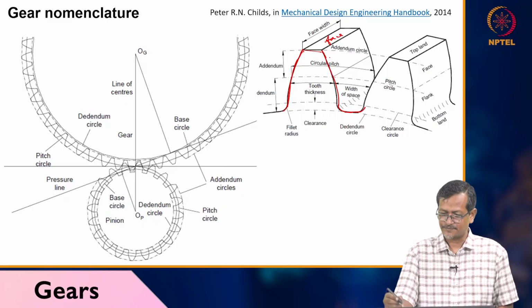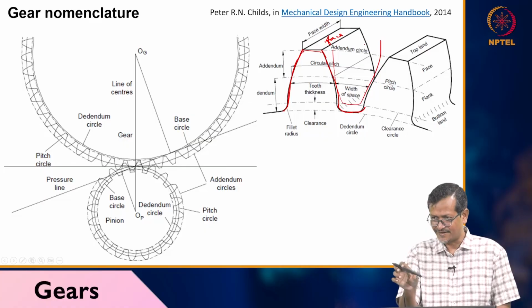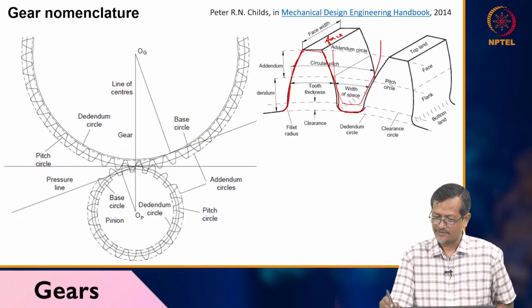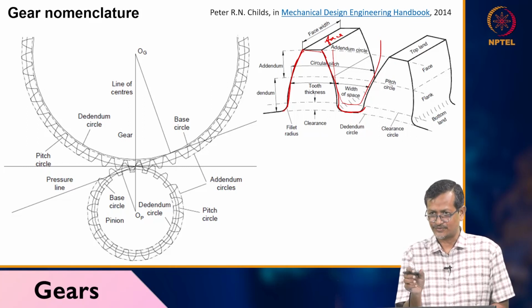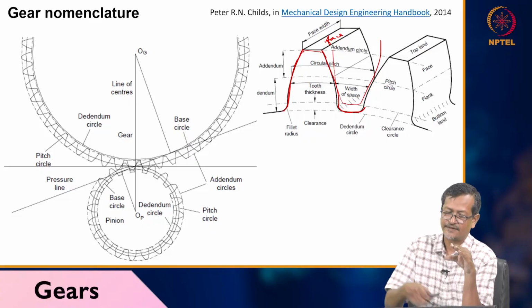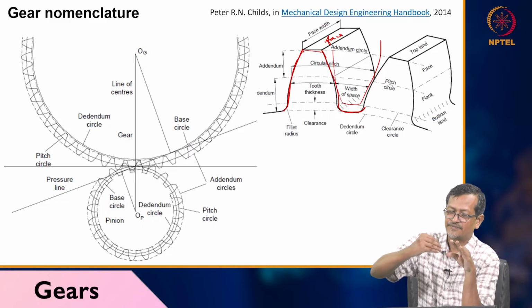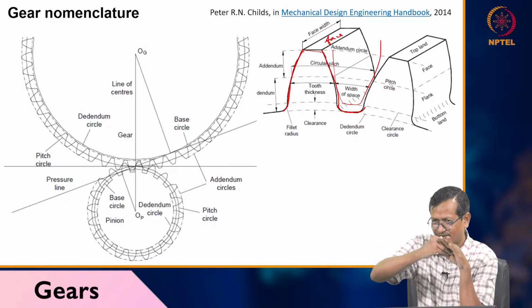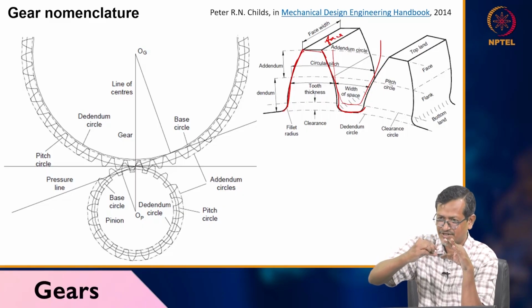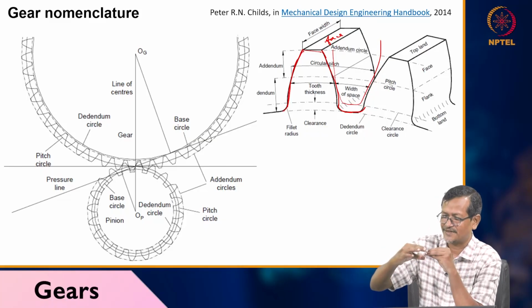The other gear will come and mesh like this. It will fit exactly, and again it will be sliding up. Then it will have reduced friction and it will not be locking. If the dimension is different, say one gear has this dimension for the teeth, it will mesh properly. But if it is very thin, then it will not enter, rather it will be locking here and give higher friction. So shape and size must be the same. The opposite must also hold: the gap should not be too wide or too small, it should match exactly.